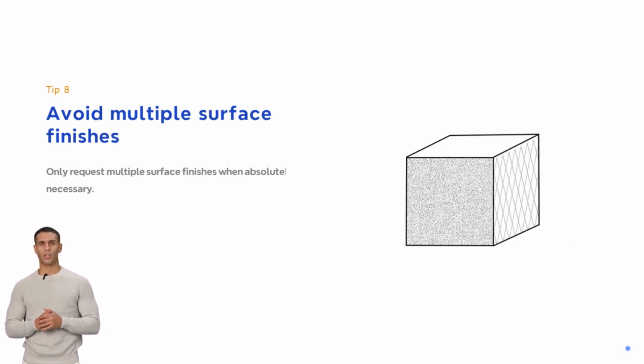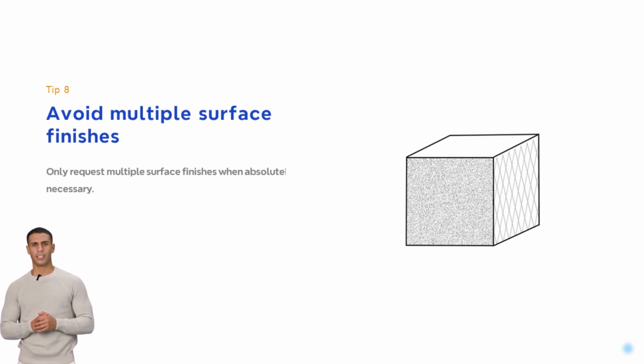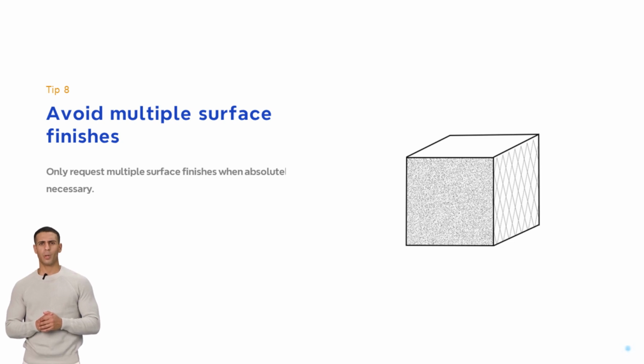Tip number 8, avoid multiple surface finishes. Only request multiple surface finishes when necessary. Surface finishes improve the appearance and resistance to harsh environments of CNC machined parts, but also increase their cost.